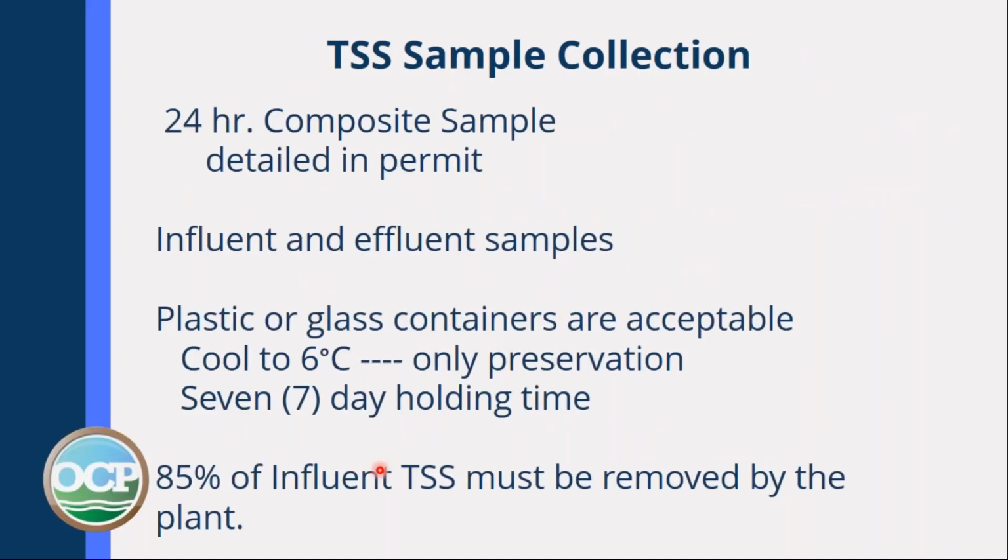The sample collection for TSS is a 24-hour composite sample, again because the amount of waste coming through is going to vary depending on the time of day. You will check the influent and the effluent to see what the levels are, because the aim is to remove 85% of the influent total suspended solids during the treatment process.